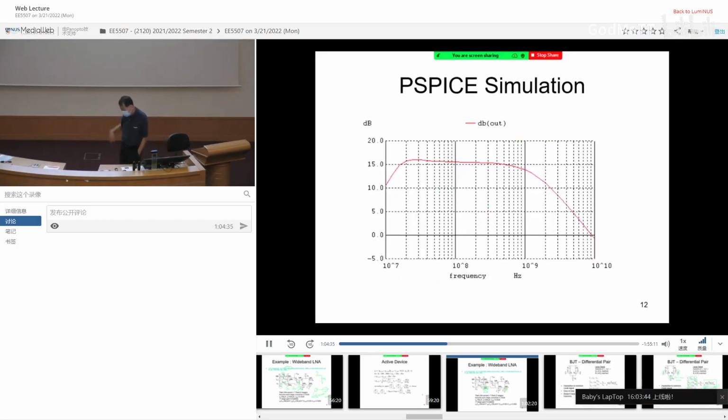So of course, all this is ballpark calculation. Nothing is accurate. So once you get this calculation, you put it into the schematic and simulate. Okay? Once you simulate it, you will start to adjust. For example, you find that, okay, for this amplifier, the gain is about 15 dB, pretty close to what I want. The bandwidth is also close to what I want, about 900 meg. Okay, it seems like I probably don't have to do anything, but if it's short, then let's try to adjust. Maybe I try to lower the resistance and pump more current, or get the resistor larger and make the capacitor smaller, and so on and so forth. So you can try to fine tune, but this basically gives you some ballpark figure of how to calculate to actually get what you want.